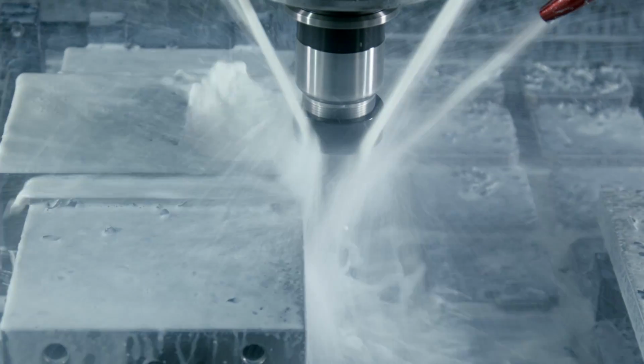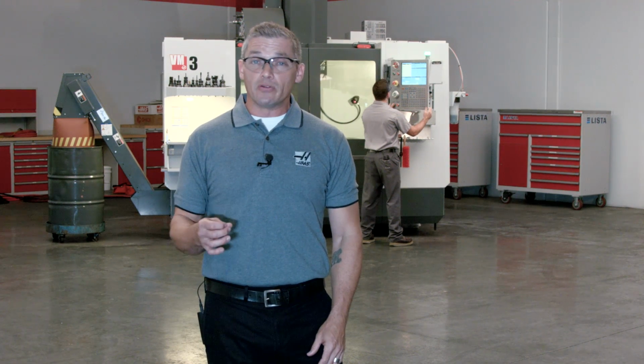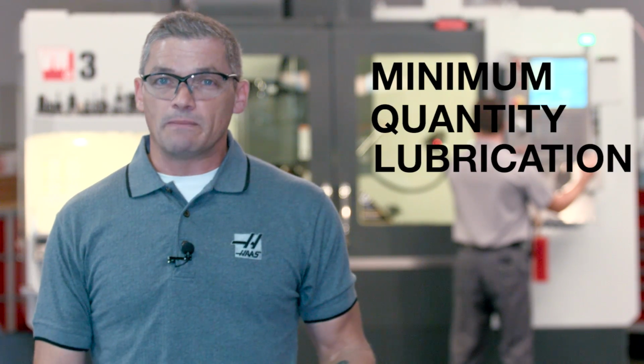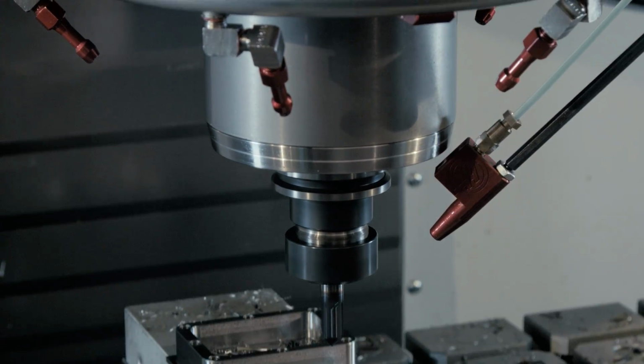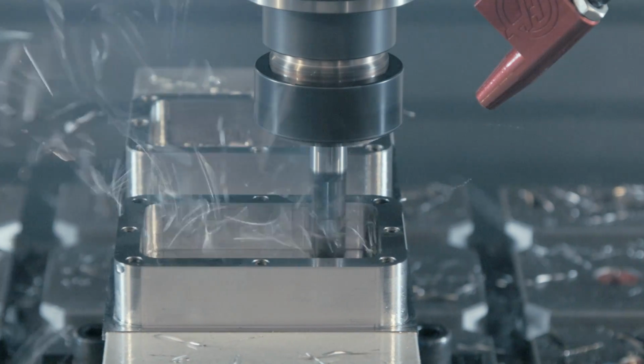Most every machinist is quite familiar with running flood coolant. But in recent years, more attention is being paid to another means of keeping your tools sharp while you're cutting. It's usually referred to as minimum quantity lubrication, MQL for short. Use a stream of air to deliver a fine oil mist to the cutting zone and deliver just enough oil to make sure the cut is adequately lubricated.